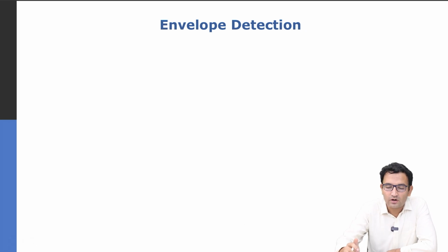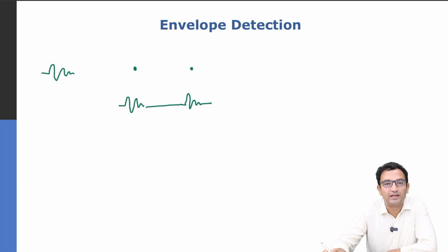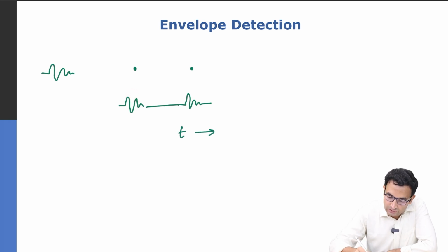So you'll recall we talked about envelope detection very briefly. We said that if we have, let's say, a target and we send an ultrasound pulse like this, then after a delay, you would receive a signal like this, right? Now, what this tells us is that at this location in time, and I can convert from time to space by using the speed of sound, right?